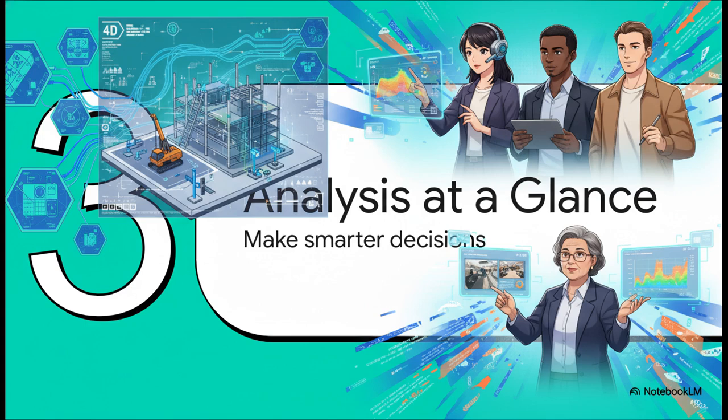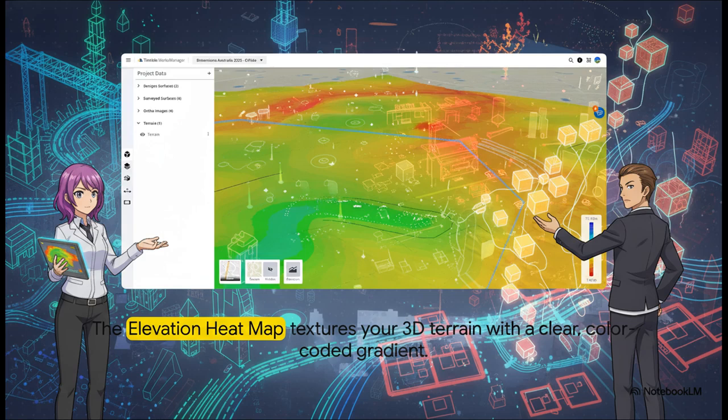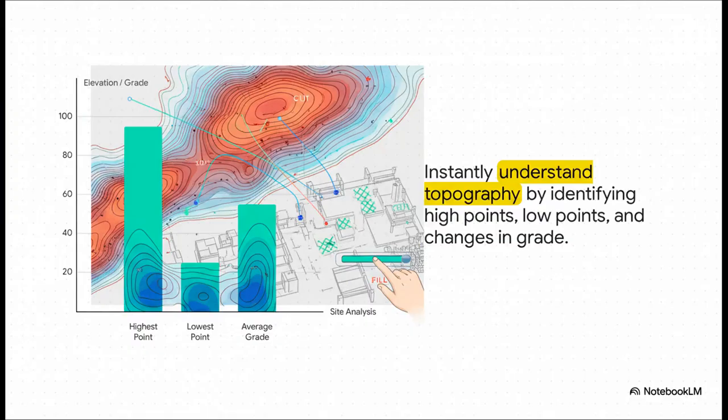So, we've unified all the data, and we've given it this amazing photorealistic context. But the real value, the real payoff, comes from what this lets you do next. It's all about making smarter decisions way faster than before. Take the elevation heat map, for instance. With just one click, the system textures your entire 3D terrain with this color-coded gradient. So instead of trying to read a bunch of confusing contour lines, you can instantly see the site's elevation profile. This turns your model from just a visual into a powerful analytical tool. The red areas are your highest points, the blues are your lowest. Right away, you can understand drainage patterns or figure out the most efficient haul routes before a single machine even starts its engine. We're talking huge savings in fuel and time.